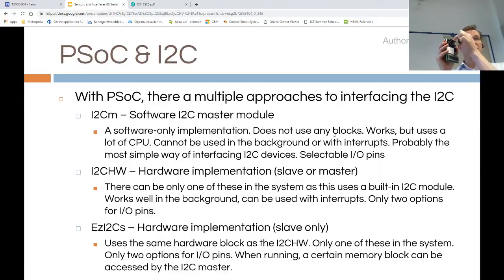When you set the reset pin, then this device actually transforms into I2C memory. And this programmer is just pushing the data to the I2C memory here. The flashing is done that way. No brainer. That's why these are something like €1 each.